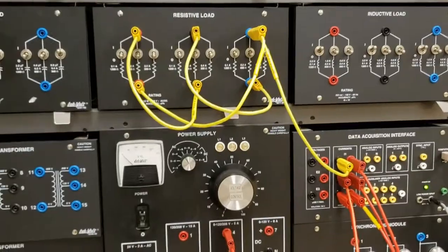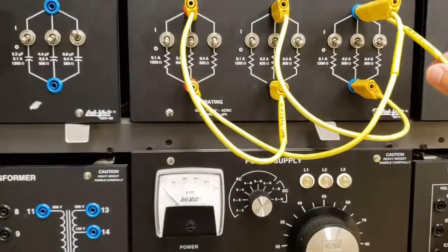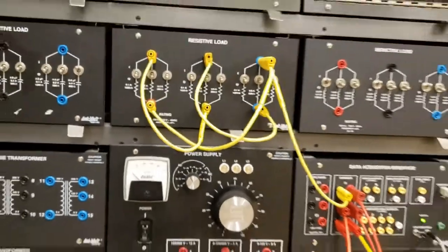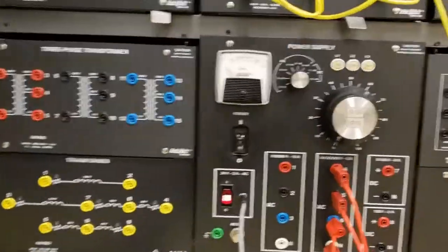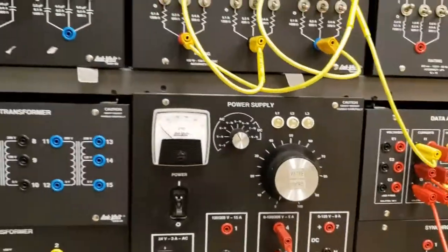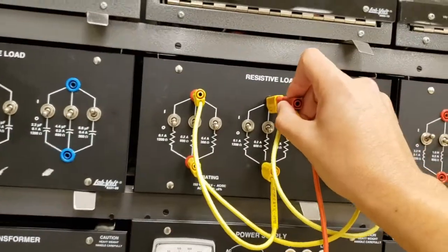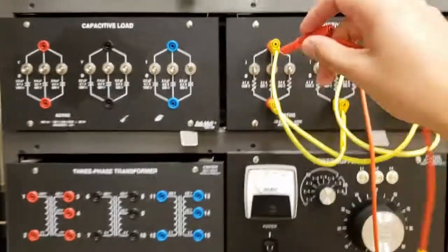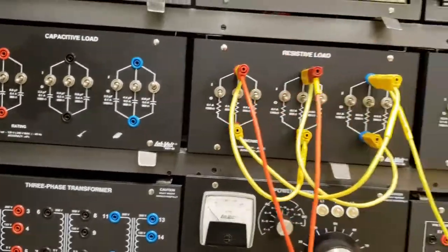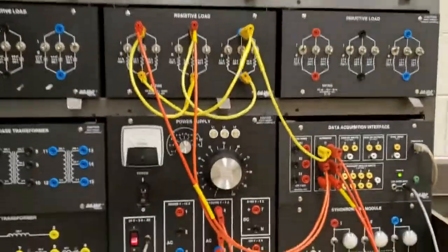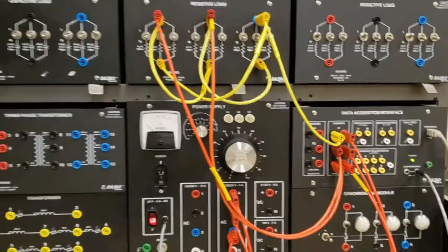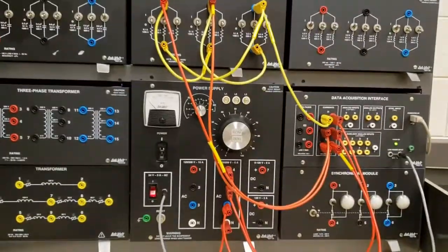All right, and then you're gonna connect your power supply, your powers to each of the top terminals. And that's pretty much it. I'm gonna go ahead and do that right now, real quick. So you can imagine this is the 4 terminal, this is the 5 terminal, and this is the 6 terminal. And if you want, you can go ahead and draw a delta configured load, draw your 3-phase power, and see if what I just said makes sense. And hopefully it does. Hopefully I wired this up correctly.